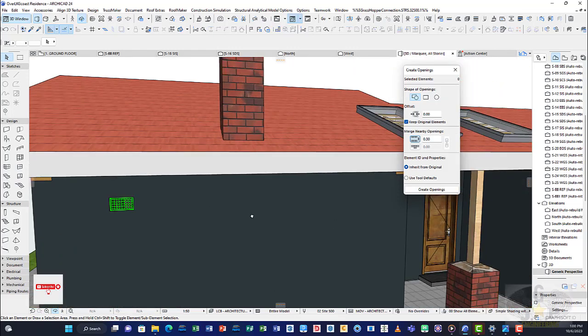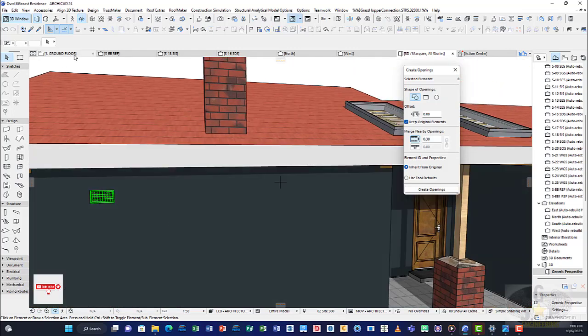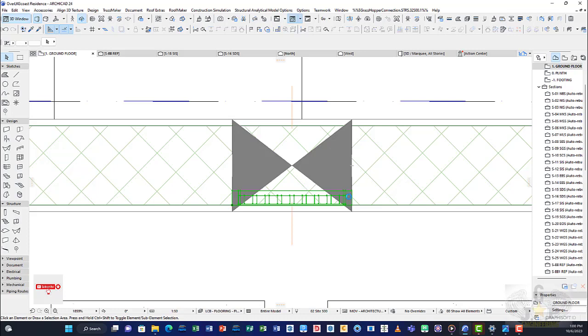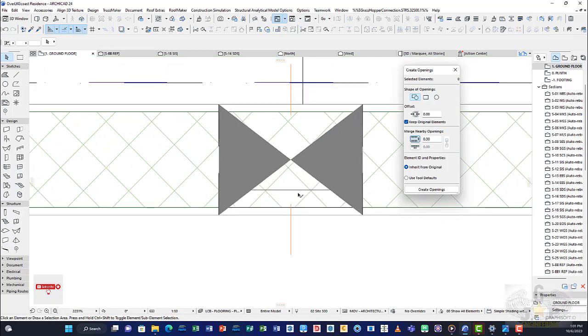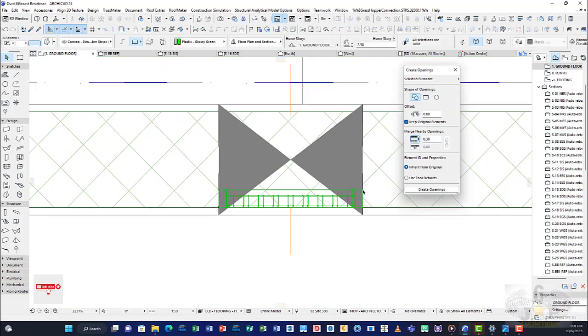Okay. What are we gonna do next? I'll go to the ground floor. I want to create a copy. So I'm going to mirror this element, I'm going to mirror our grid. So I click on our grid, click on one of its corners, wait for the palette to appear, click on the mirror command, hover in the middle here, click and create the mirror. I press control down for the copy and click.